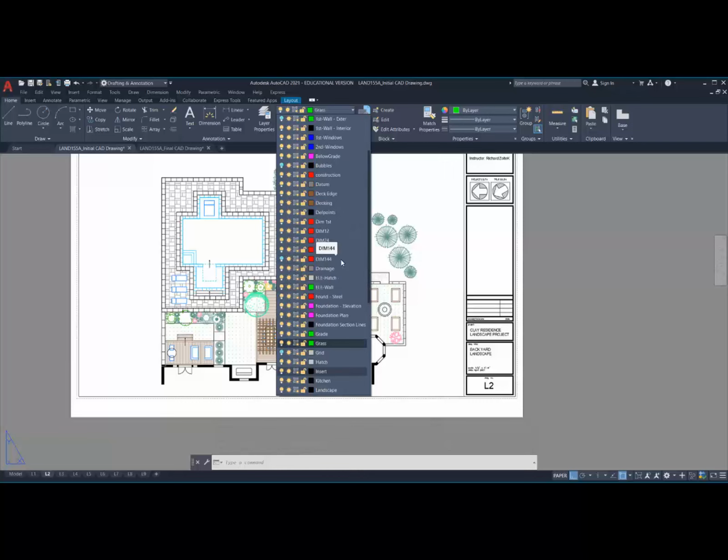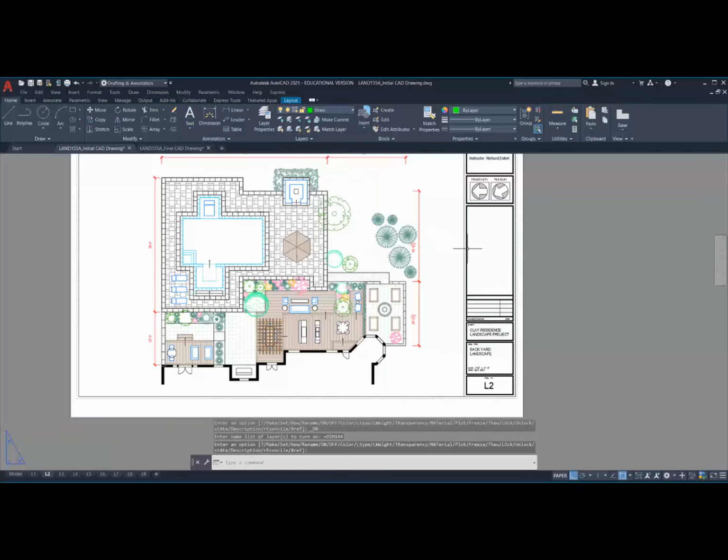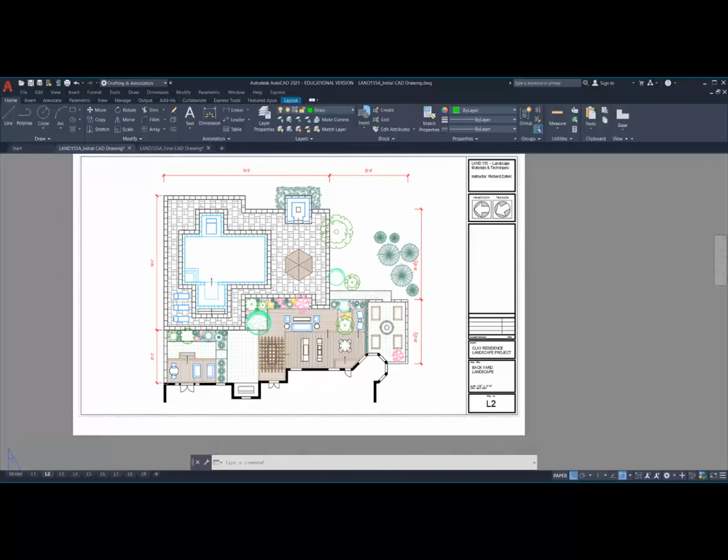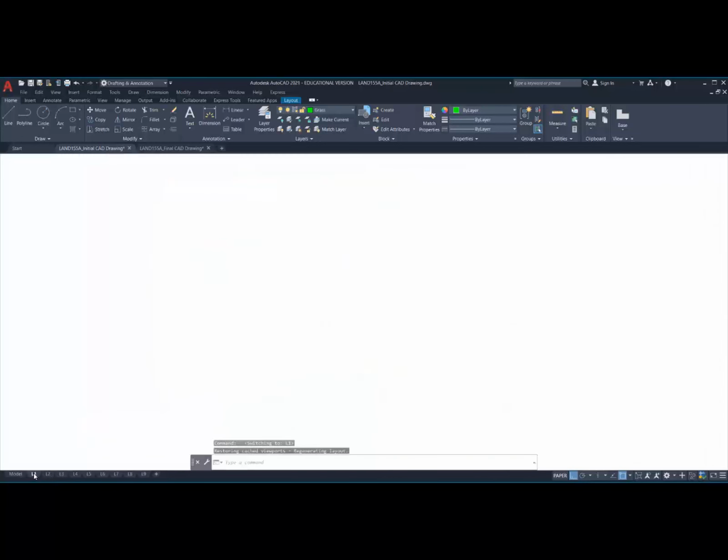And then you're going to add some general dimensions. And what these dimensions do, they're just overall dimensions. Notice again, they're on different layers, so I can turn them on and off easily. And what this does is it gives me the general sizes of the massed areas, or the specific areas or grouped areas. And you can see how it's just along the two sides and the length. So not the side of the house, but the other two, just to give some general dimensions.